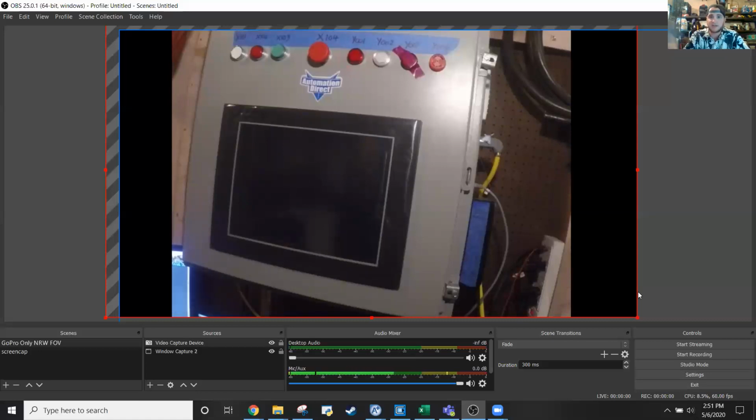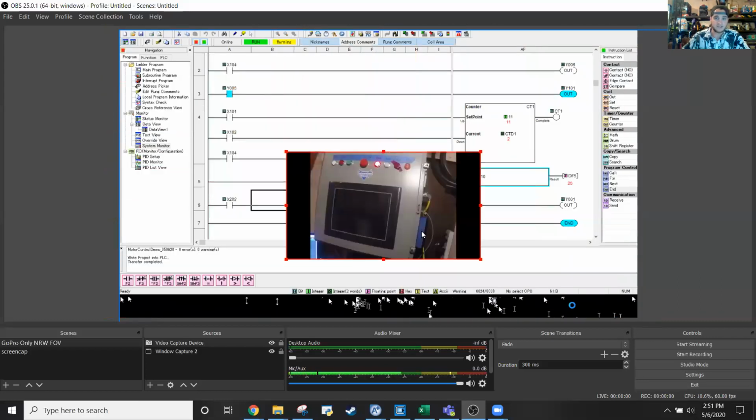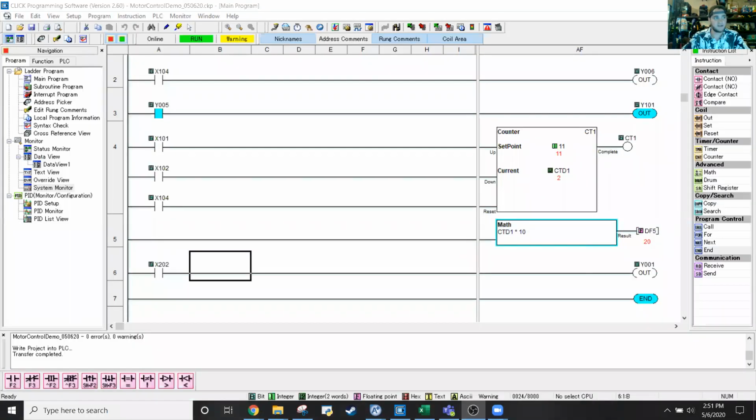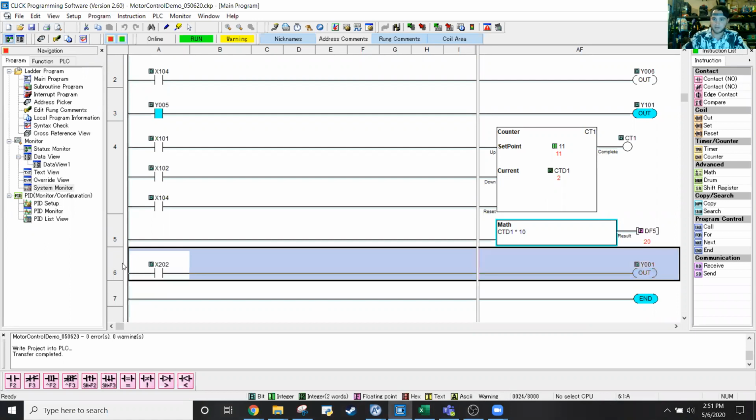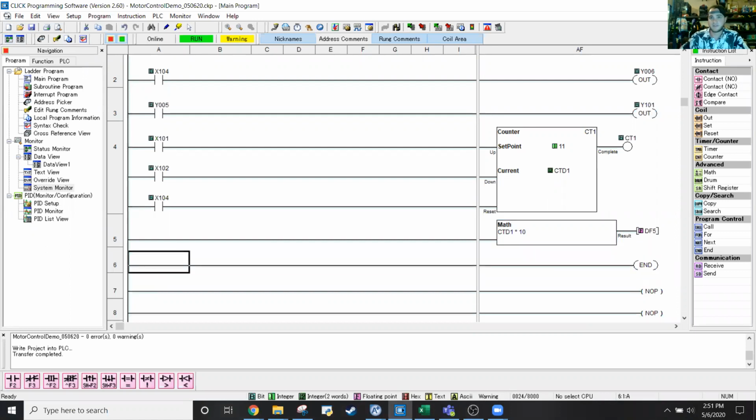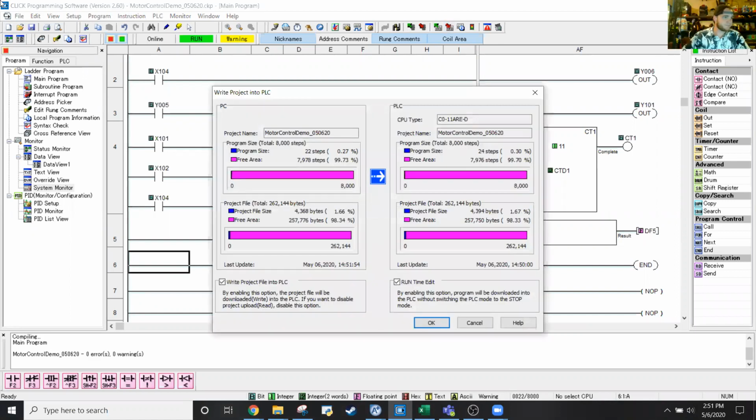If you do this, it might take a year, it might take 5 years, but eventually that relay contact is just going to burn out, because it's not really intended to cycle fast like this all the time. So another fun fact to keep in mind, that's a total tangent and not really super important to what we're talking about, but good information to have. So in order to save our poor relay, I'm going to hit the stop button and kill it.